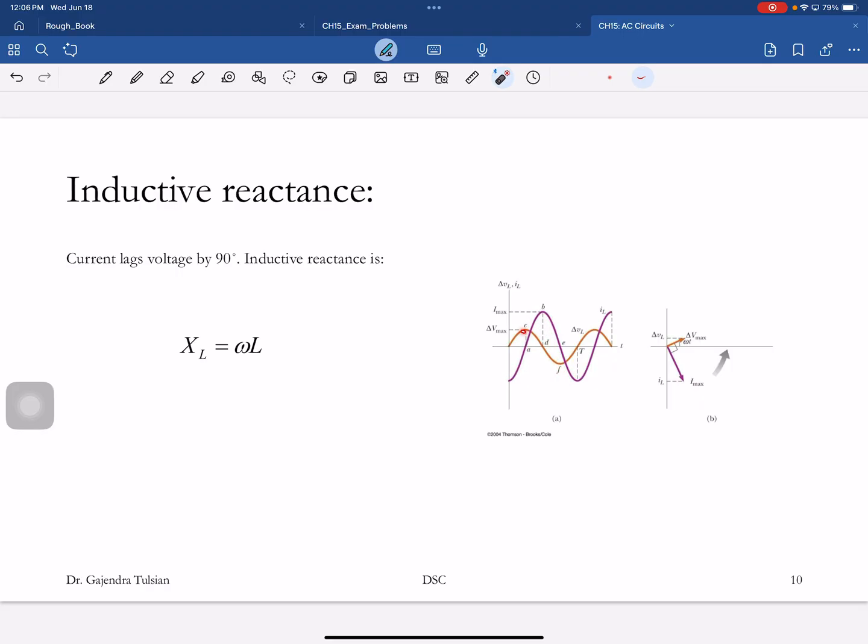See, in this part, the voltage is decreasing and the current is increasing. And so on. Anyway, they're not in lockstep. So there is the voltage phasor, and there is the current phasor. All you do is rotate it at angular speed omega, and if you want the instantaneous value of the voltage across the inductor, you take the y component of that. The instantaneous value of the current is the y component of that phasor.